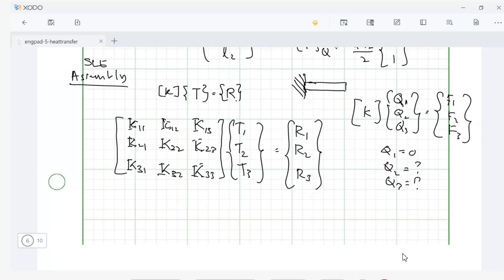And again, if you recall correctly, some of the problems we had, for example, Q3 is being restricted. Say this thing is Q3, and Q3 is limited to maybe 1.5 mm. So this is what we call the homogeneous boundary condition, and this is what we call the non-homogeneous boundary condition.